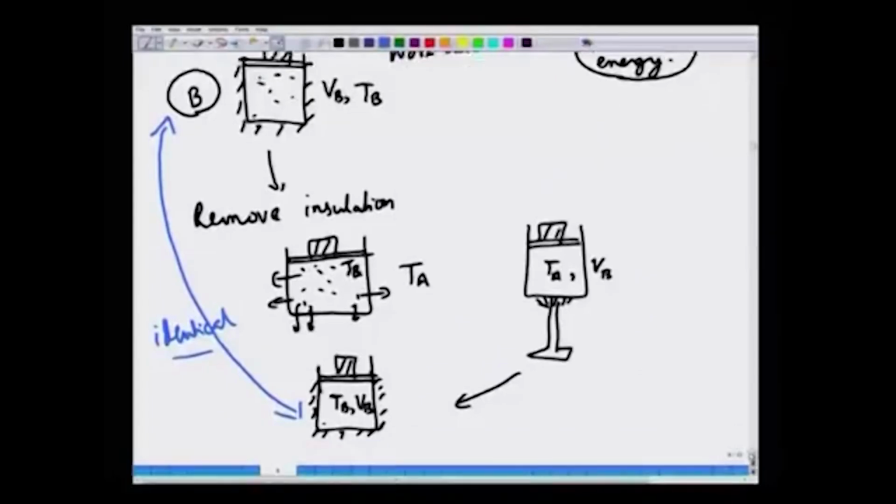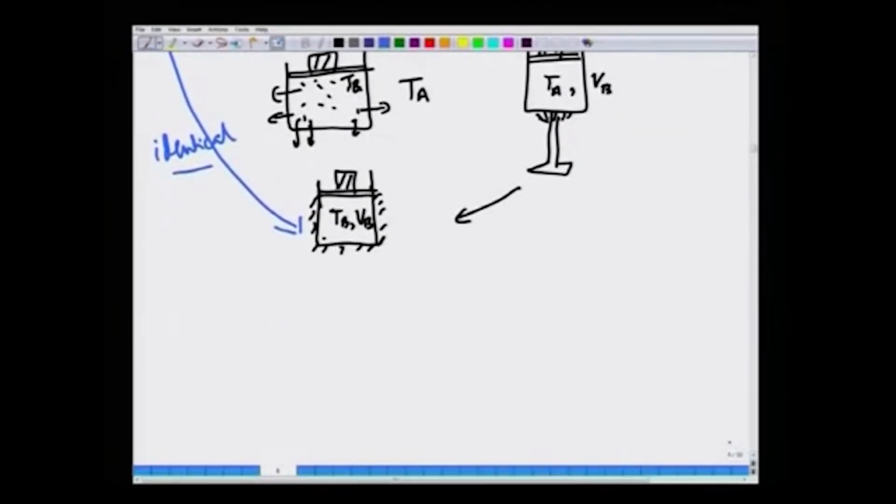Okay. So, what is important, and this is the important lesson from the first law of thermodynamics, is that fluid systems such as a piston cylinder assembly containing gas, a macroscopic system with innumerable molecules, are characterized not just by their gravitational potential energy or their macroscopic kinetic energy of motion, but they are also characterized by their internal energy, and this internal energy can be changed by doing work, as we have seen, or by exchanging heat.